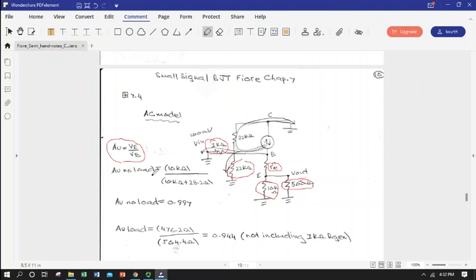So we can define an unloaded gain, literally, just using a KVL expression. So we can say V sub E would be just our collector current, if say we took the load resistor away and we just had an open, we didn't let any current flow through the load.